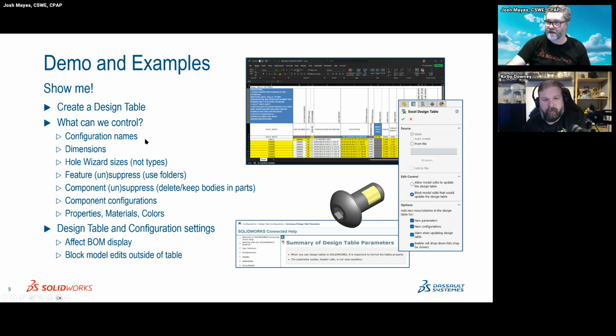If anyone's used Toolbox, you know, SolidWorks gives us a pretty nice database of hardware out of the box, as long as you're using SolidWorks Professional or higher. And so I ran into this with my last job where we had all of this hardware and we were starting to incorporate, you might ask what this little yellow patch is here. This is a nylon patch, and it's a liquefied nylon that's applied to the hardware, and it avoids us having to use liquid Loctite. So I didn't know how to represent that using Toolbox.